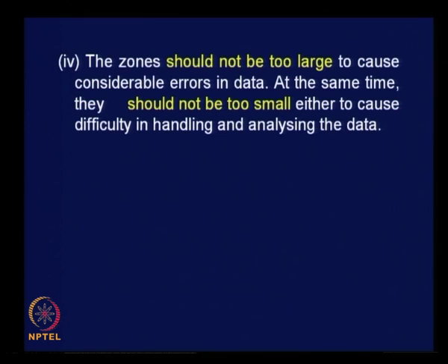At the same time, they should not be too small either to cause difficulty in handling and analyzing the data. So you should not be too ambitious and divide your urban area into 10,000 traffic zones. You will be unnecessarily troubling yourself for no net advantage. Okay, you have to be careful.